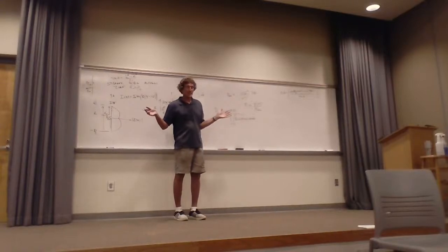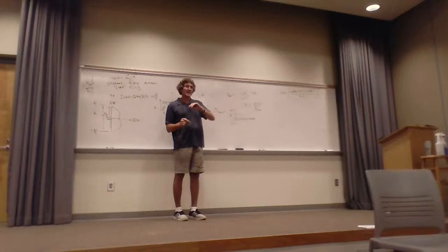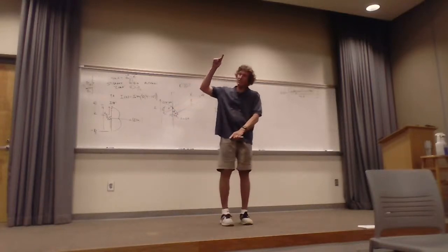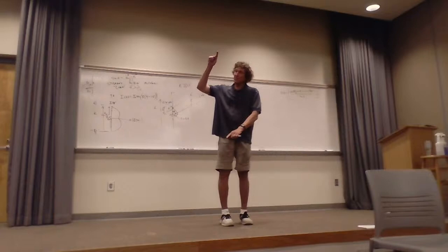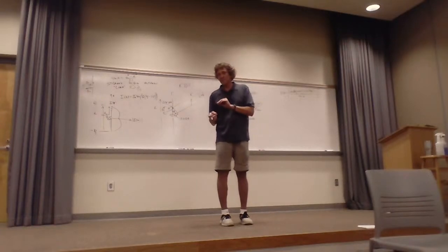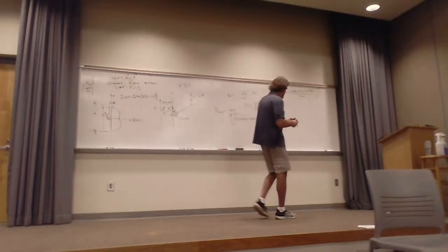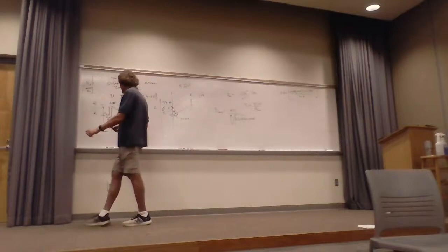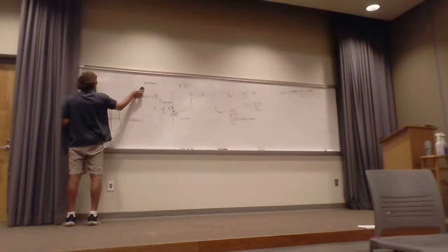But that's all right. There are some standard sized antennas that are used everywhere. The first of the straight wire antennas is the half-wave dipole. Have you all heard of a half-wave dipole? Well, a half-wave dipole is just half a wavelength long. And the beautiful thing about it is it has a high radiation resistance, and it has beam characteristics that we appreciate. Trust me on this. Dipole antennas are used everywhere.